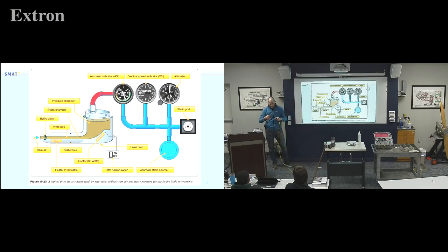Ooh, no. I absolutely would not want to use compressed air because it's very low pressure. So that's what this is for. I haven't quite figured out the best way to seal this off because it's not perfect. But if you were to put this on your pitot tube, you could blow in here, but a lot of aircraft will say don't. So what they actually say is, here, you hold that for me, will you?